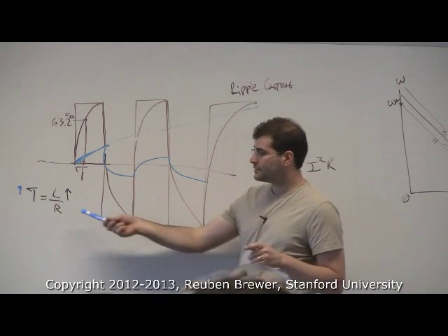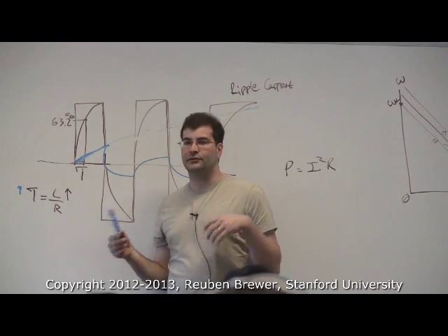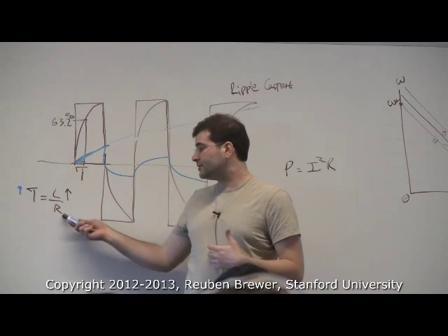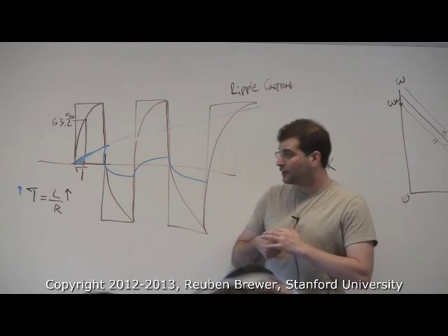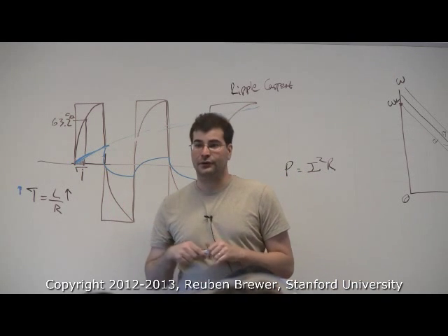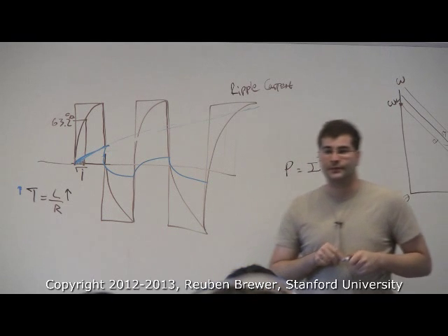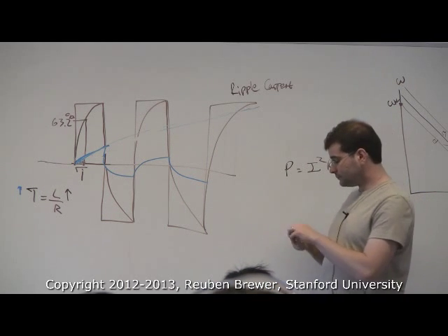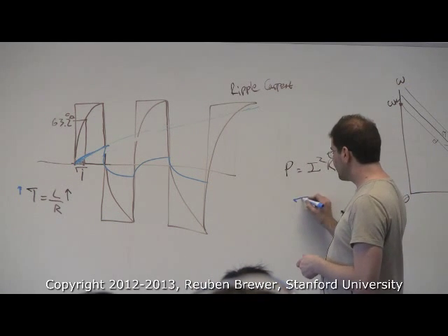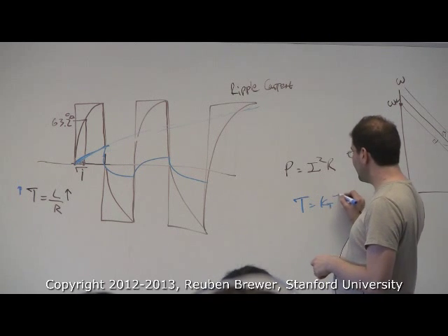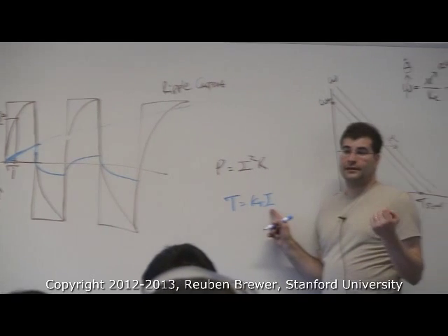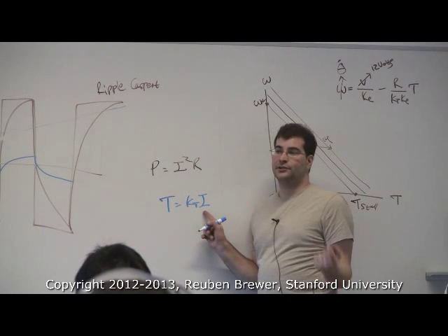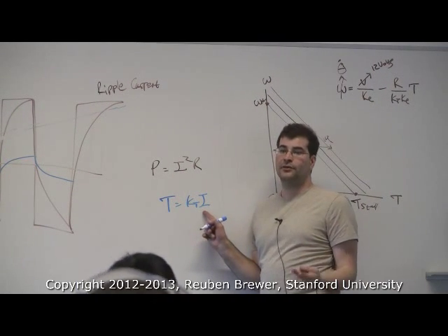Now typically this doesn't really matter that much. If you're doing voltage drives, I haven't needed to and I haven't seen other people do it. If you know otherwise, congratulations. I do this a lot for current drives for haptics. So remember, with haptics, we're doing torque equals K_T I, and we were going to buy a Copley amp that we give a voltage and it converts it directly to a current. Now there are two important things here.